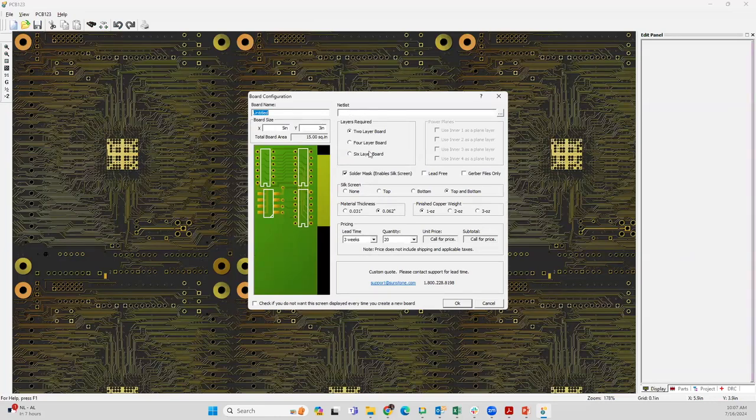And you can import a net list if you have something from your engineer that is going to work. Otherwise, you just start building your schematic. It's a 2-layer board. You can have 2, 4, 6, or you can make more. There is a trick to do that. You can define inner layers as plain layers to make them a power and a ground layer if you want.